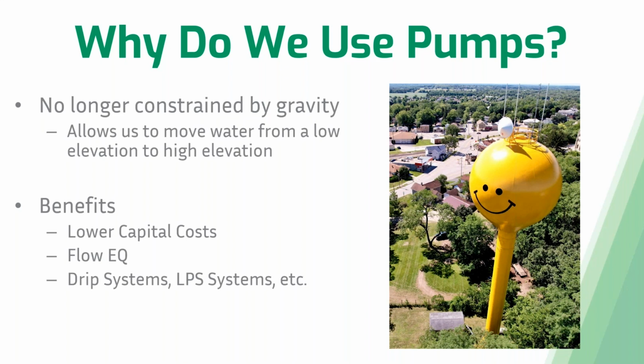Also, with pumps, you can simply install the discharge pipe below whatever the frost level is in the area and simply follow the existing grade. So excavation costs can be much lower compared to gravity systems where you have to maintain a certain slope in order to keep your water and sewage moving through that system. So with pumps being installed in very hilly or rocky environments, excavation costs tend to be much cheaper in that type of application.